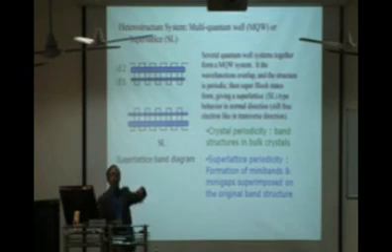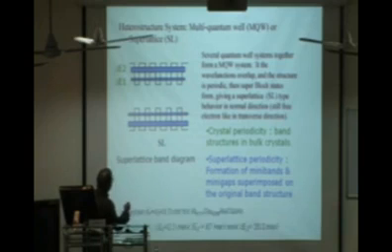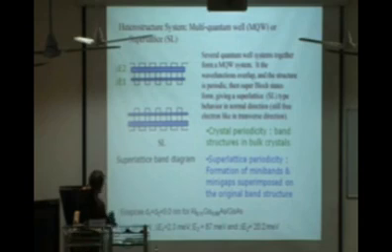So if you can make a system like this, you have tailored a material which has inter-subband transitions, or some kind of a minigap between the two levels in the conduction band, and again a gap between the two levels in the valence band. We have calculated some of these values using a combination of aluminum gallium arsenide and gallium arsenide, and the thickness of both the barrier and the well is in the range of 9 nanometer.